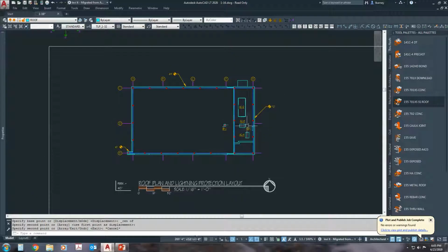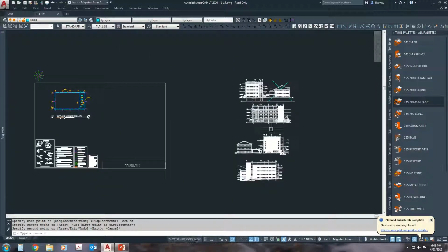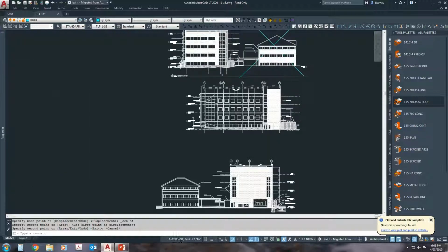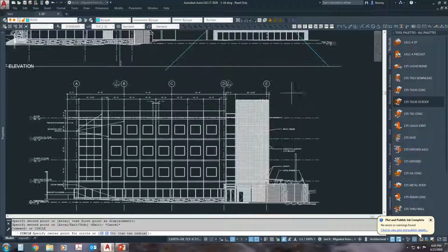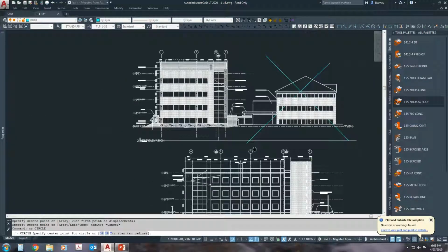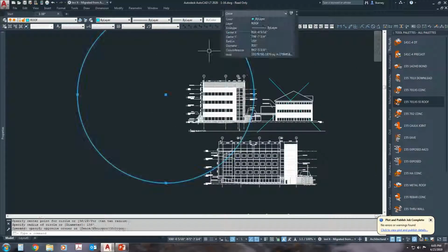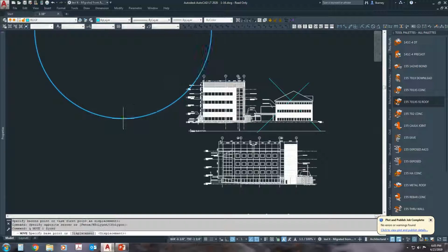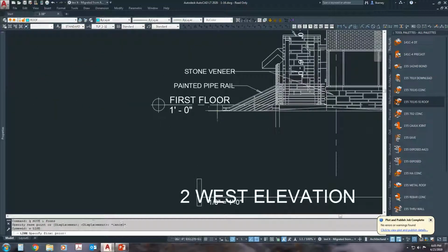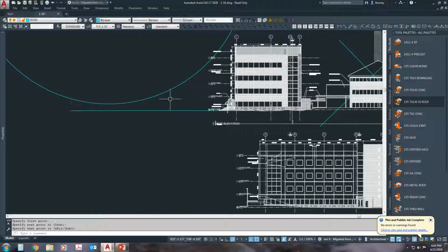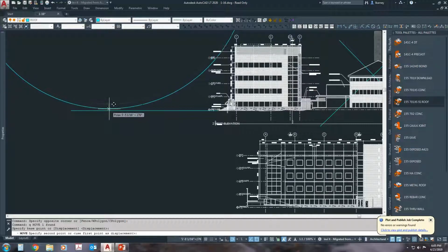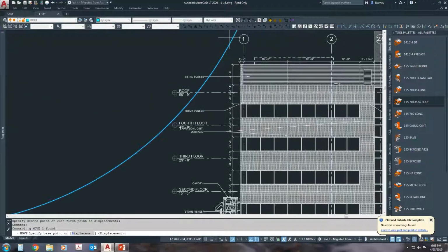Now here's an exhaust fan. So all mechanical equipment on the roof will need to be protected unless it's in the zone of protection, which I'm going to draw here. This canopy that's down below, I'm going to take an imaginary 150-foot radius arc, placing it on the ground level, and then placing it at the highest roof area.